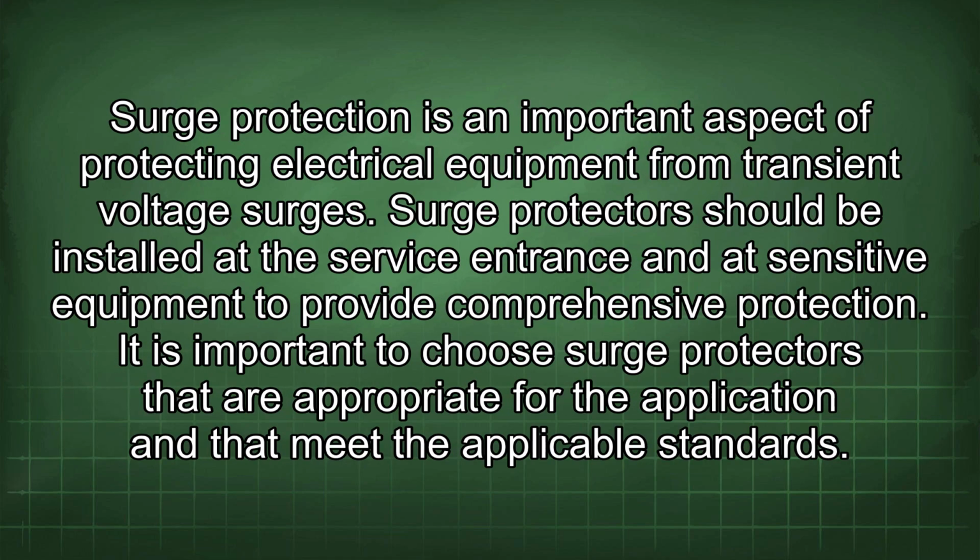Surge protection is an important aspect of protecting electrical equipment from transient voltage surges. Surge protectors should be installed at the service entrance and at sensitive equipment to provide comprehensive protection. It is important to choose surge protectors that are appropriate for the application and that meet the applicable standards.